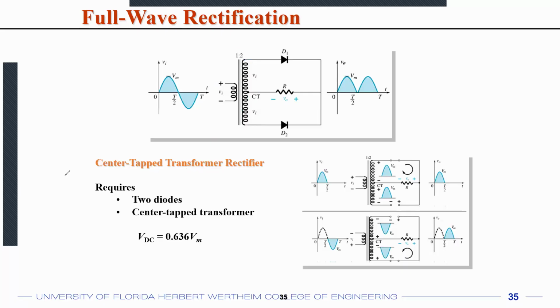So the last rectifier is like one branch of the rectifier is on at once. Because it's a center tapped, the top half is always like 5 volts, and the bottom half is always like minus 5 volts because it's tapping in the middle. So are both diodes in this rectifier on at the same time? No, that's a good question. Both diodes in this rectifier are not on at the same time.